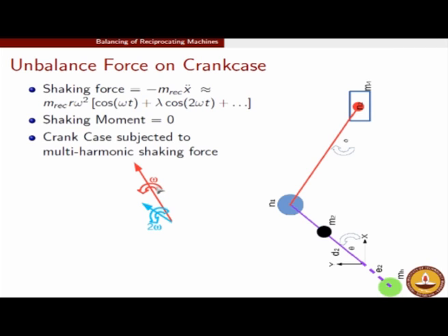But unlike a rotating unbalance, wherein we know that the forces induced will have components both in the y direction as well as in the x direction, this time we have to take into account that it is only the x component of this rotating unbalanced force which is the shaking force. So the shaking force is now construed as the x component of the rotating unbalanced force.